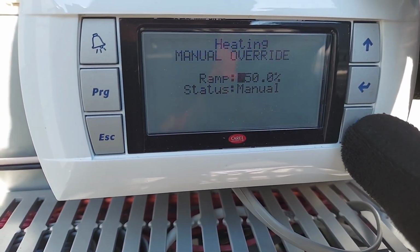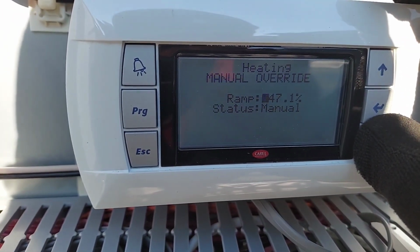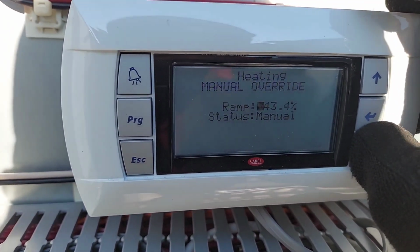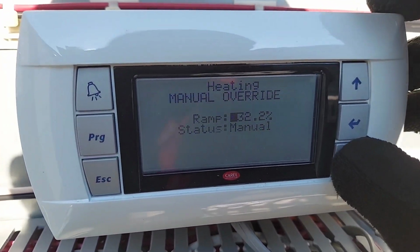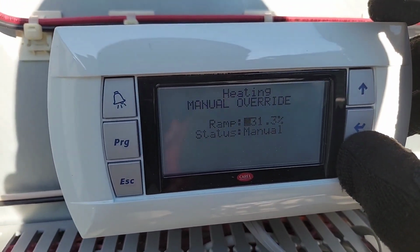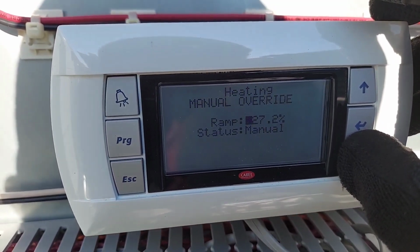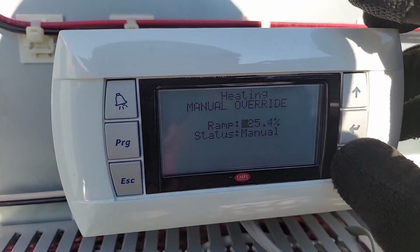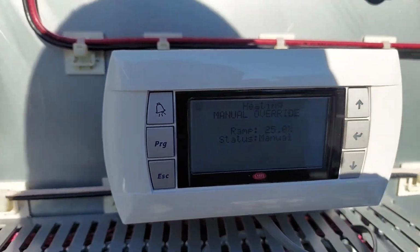We can go to like 25%, right? It's gonna be an even smaller flame. This is a modulating furnace. Let's see if we get lower pressures on our manometer if I go to like 25% heating. So that's how you use your manometer. That word always ties my tongue, man. Yeah, 25.